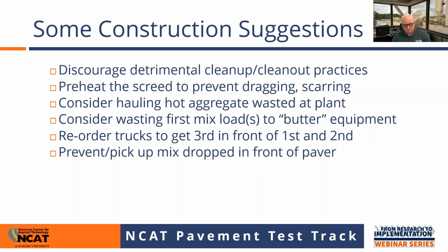This is really kind of basic paving practice, but I think it's super important for OGFCs because it is an open mix. It's a relatively thin mix, and it has a lot of air in it when it's hauled and when it's placed on the roadway. So you lose a lot of temperature in it, and we tend to not think much about mix that we spill or drop out in front of the paver. That can be from transferring into the shuttle buggy, or just material that falls over the edge of the hopper insert or whatever.